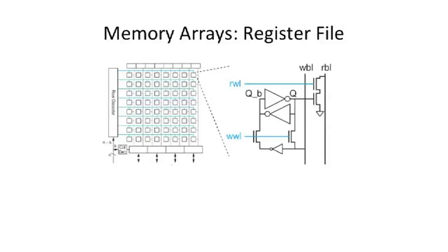In order to have this work, we're going to energize or ground the write bit line such that it's stronger than what either of these inverters can drive. So we overpower the inverter, and we can flip it, let's say, from a 0 to a 1 or a 1 to a 0. So this is not traditional complementary logic, but this is how we typically build register files, small little arrays that are close, let's say, to a processor.